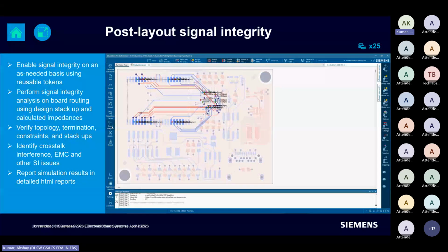Now, we discussed pre-layout. So of course, we should not forget about post layout. Once your board is done, once you have completed your design, you can export it for signal integrity analysis from the physical layout perspective, right? Again, as mentioned previously, this is going to be a limited subset of HyperLynx features. If you want the detailed or complete features of HyperLynx, then you will have to purchase a separate module of HyperLynx, SI/PI or thermal, right? But the feature we are talking about at present is included as a part of Expedition Standard.